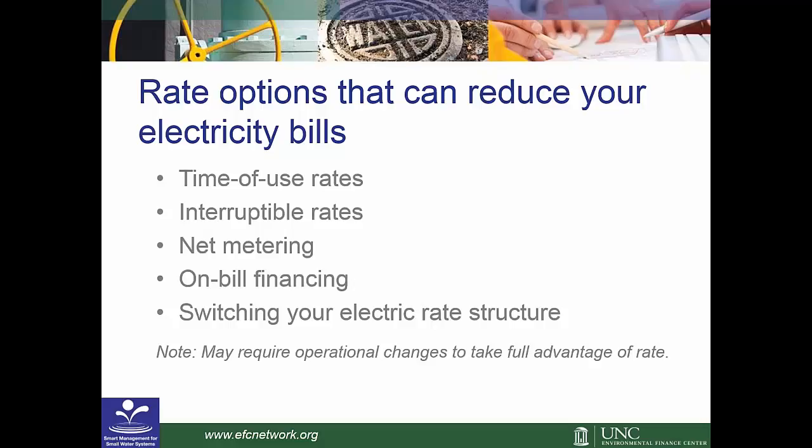Time of use rates also might mean not just time of day or time of the week, it might mean the season. There might be higher electric rates during one time of the year versus another time of the year. There are such things as interruptible rates. You typically have to opt in for them. I think we were talking about that a moment ago, where you give the electric utility permission within certain boundaries, certain restrictions that are agreed to contractually, to where they can reduce or terminate your power use altogether. I think frequently these interruptible rates are not good for water systems because of your absolute requirement. You have to meet your level of service to deliver water to your customers.